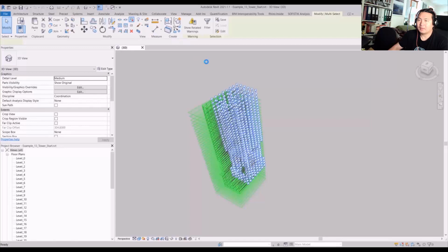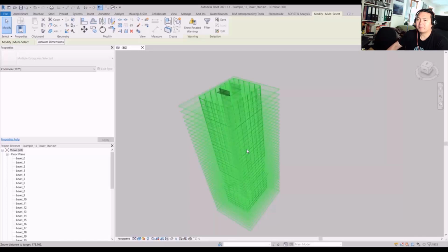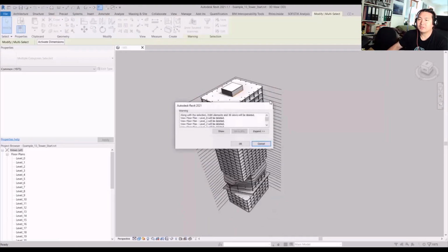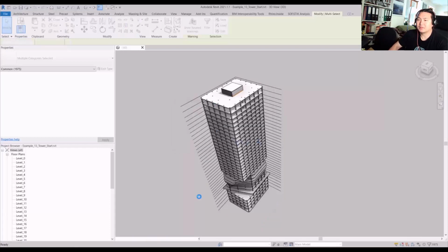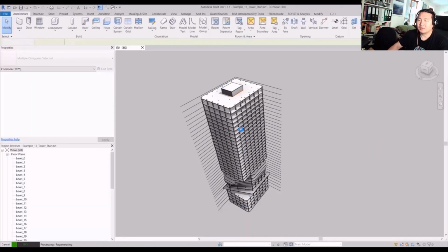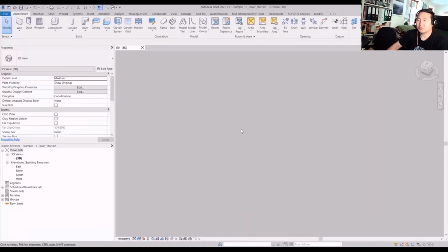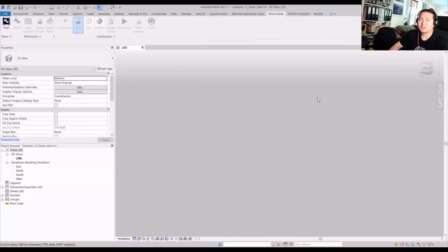And in this prepared example, back then I used Rhino Inside Revit before 1.0. So there was no element tracking method introduced back then, but now you don't have to manually delete all these generated elements. You can basically set the tracking options in your Rhino Inside Revit components, and any kind of design adoptions will be automatically updated. But back then I had to delete the generated elements to regenerate.